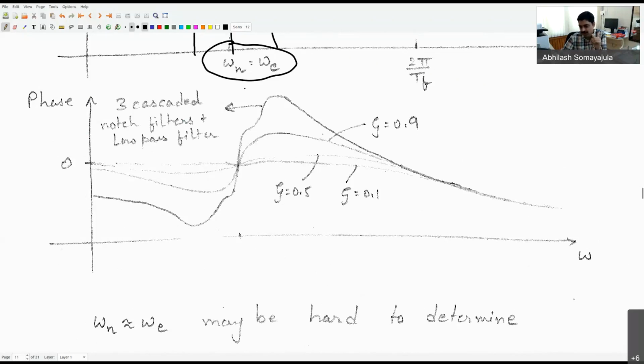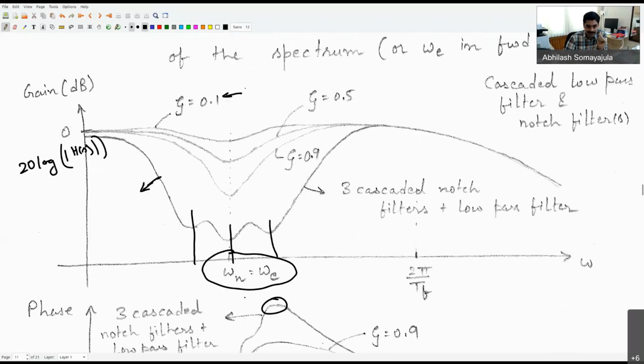But as long as they are all attributed to wave frequency effects, it doesn't make much of a difference, because even though these components have very large phase differences, the effective amplitudes are much smaller. Our interest is that the low frequency content which we really want to compensate for can be effectively compensated without much phase difference.